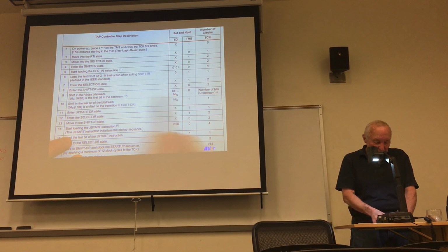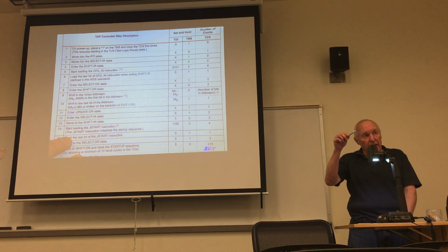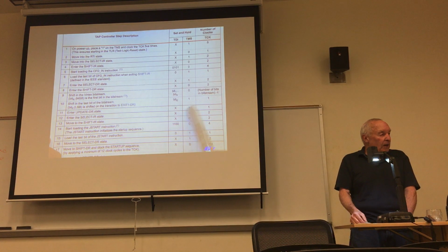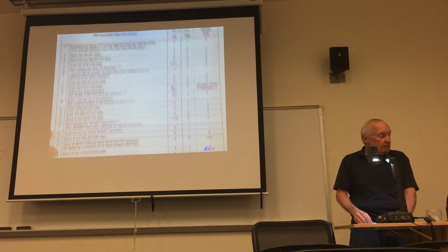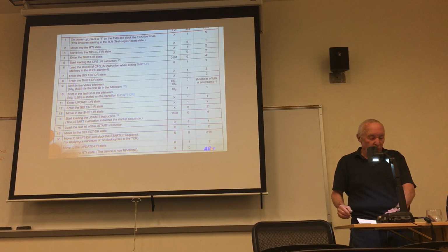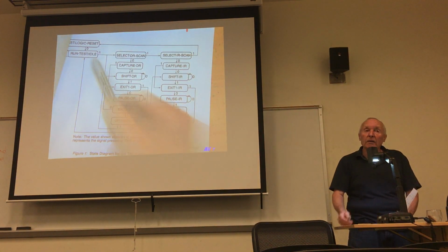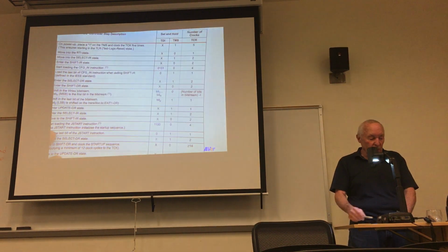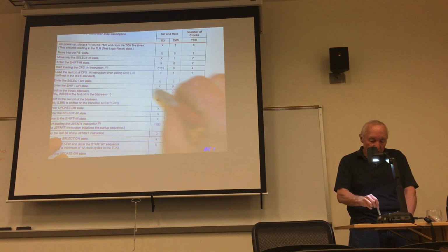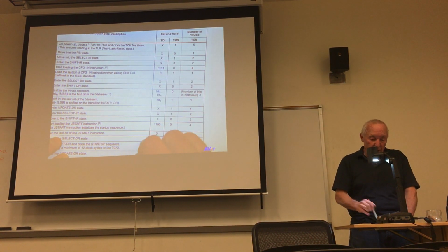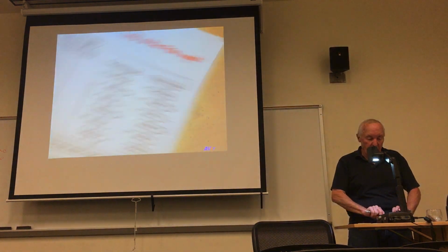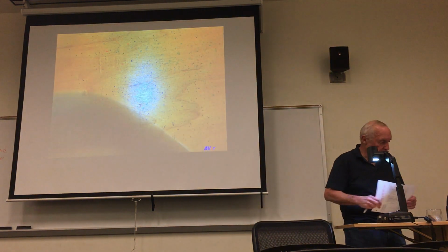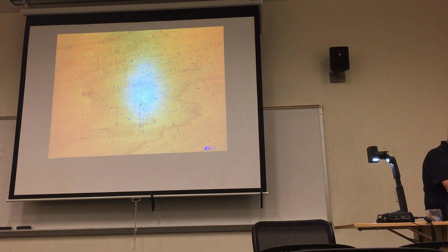So it's in this step 9 that you actually get to clocking in the configuration information. Then after you've got all the information in, then these are the cleanup steps, and you go through to 19, where you return to the RTI state when you're done. So these are the steps you would go through to actually program the FPGA through the JTAG interface.